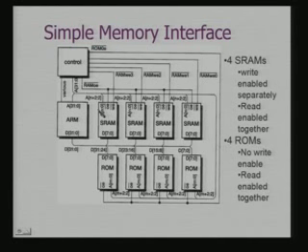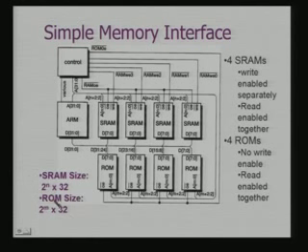And the reason why the last 2 bits are not being used is that if these are all 32-bit word data, and if there are byte addresses and they have to be located at a 32-bit boundary, then the last 2 bits actually become redundant. Okay. And this is a common data bus to which both RAMs are connected. Okay. So, effectively it is in terms of 32 bits.